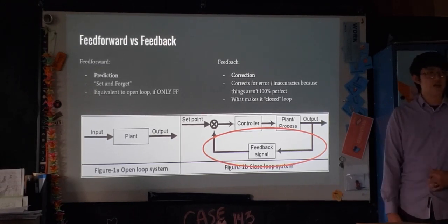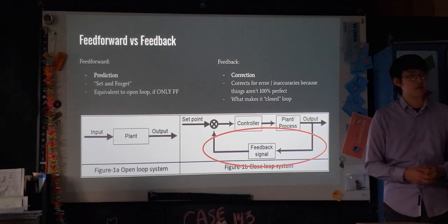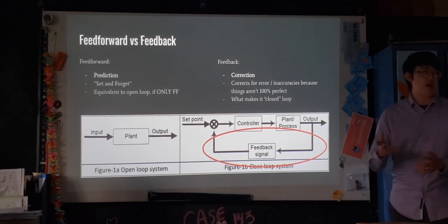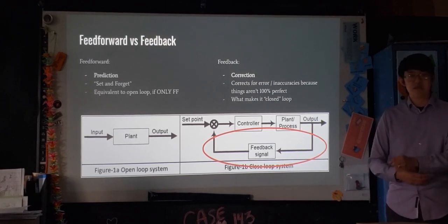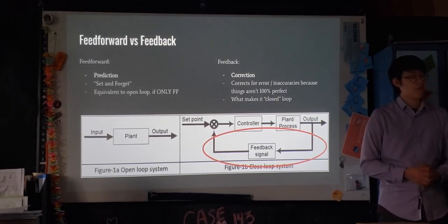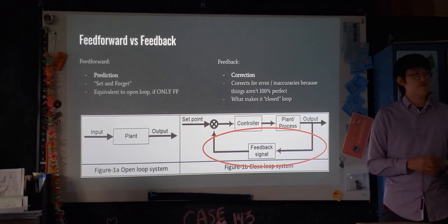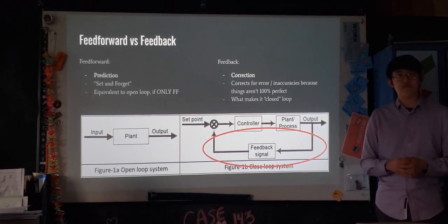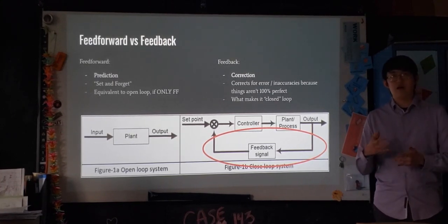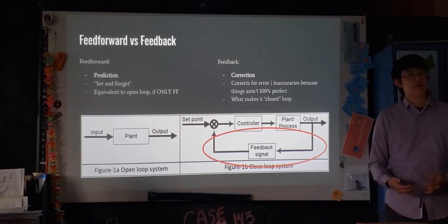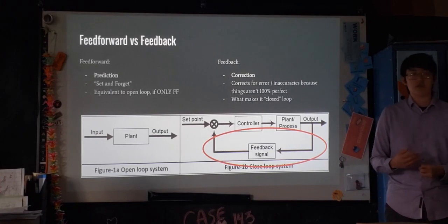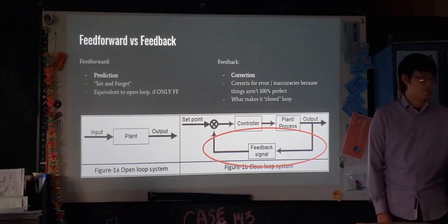SysID runs a series of tests, like testing how the motor turns and how it resists acceleration and whatnot. And from those tests, we get constants that, plugged into some mathematical equation, will tell us a little information about the robot, and that goes into the prediction algorithm.